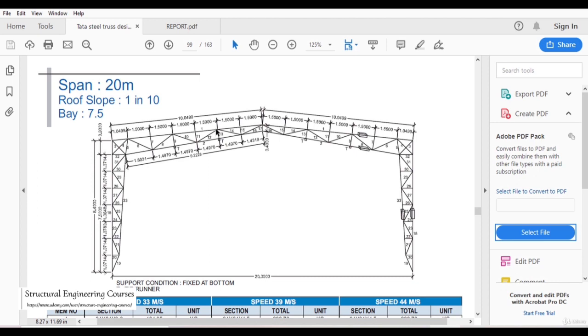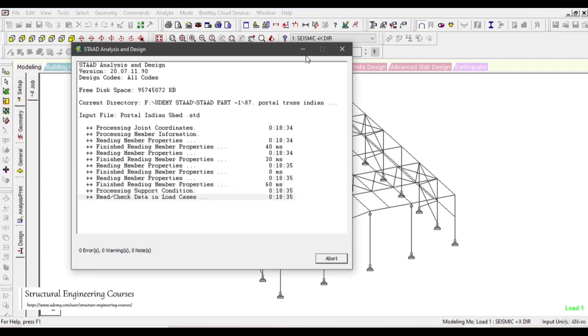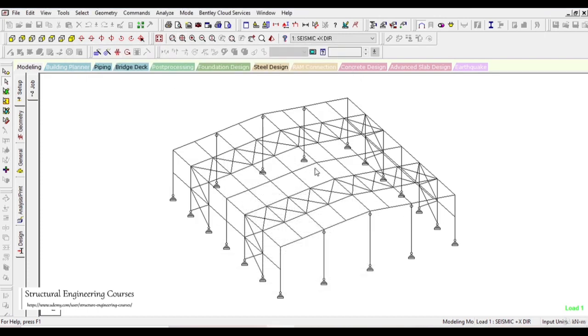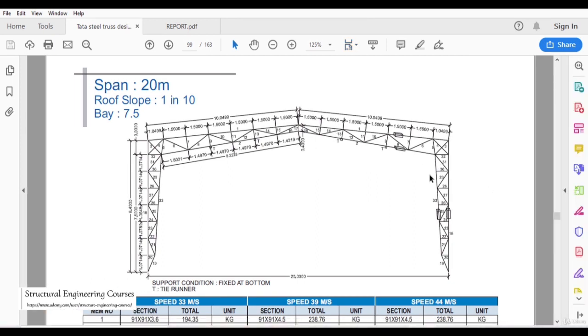Instead of the bending moment, instead of what was happening in our structure here, where if you remember, all the forces were becoming in the shape of the bending moment that we are talking about, in this structure all the forces will travel in tension and compression only. No excessive bending moment will come on any part of the structure. So these are the simple basic fundamentals that you should know while designing steel structures.